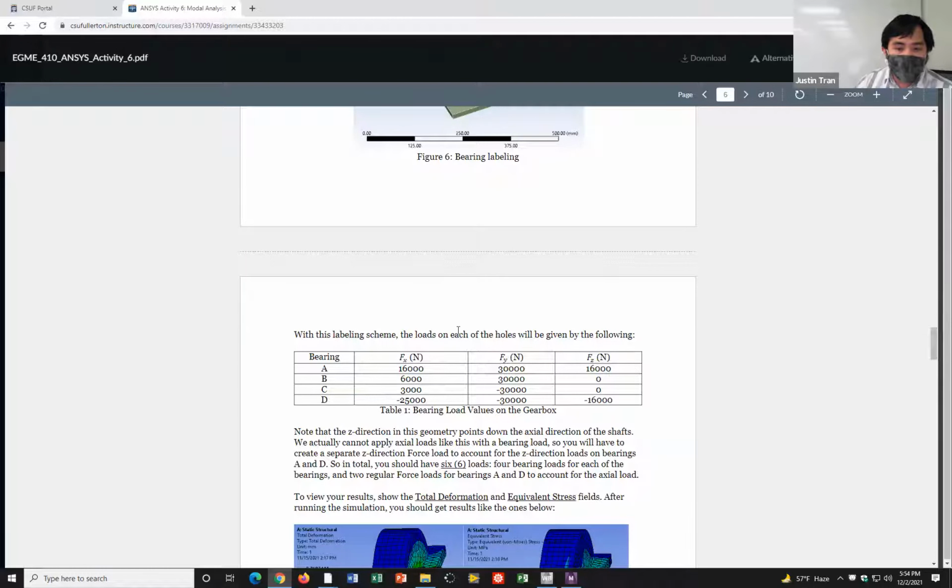All right. So does that make sense about what bearing loads are and the reason why we can't use axial loads on them? Good question. So then, did you still do it in component form and running negative 60,000 for the Z? For hole D, I do that. But for hole A, for the axial load, it's a positive 16,000, and so you can just use the direct values from this table over here.